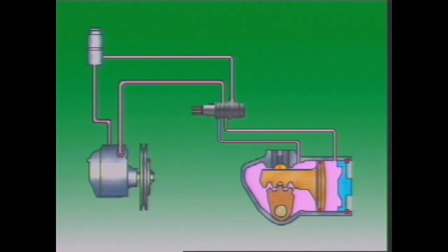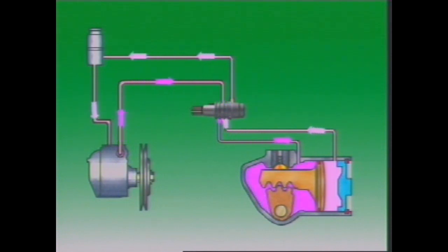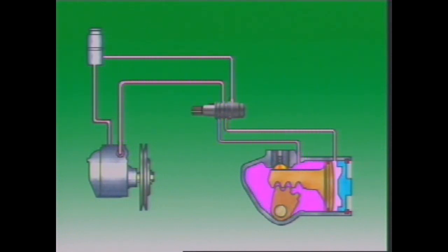In a worm and roller steering box, the piston slides in a cylinder in the casing. It has an extension formed on one side, with teeth which engage teeth on the pitman shaft. Pressure applied to either side of the piston produces a force, which is transferred through the teeth to help turn the pitman shaft.